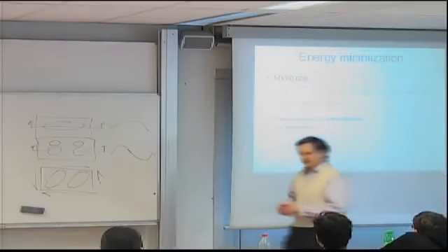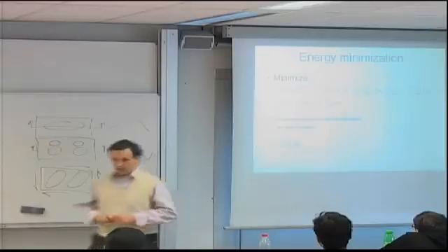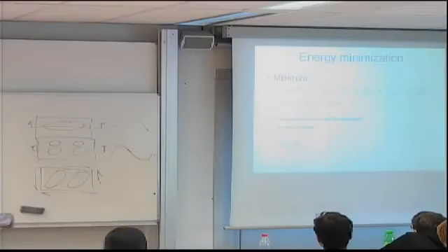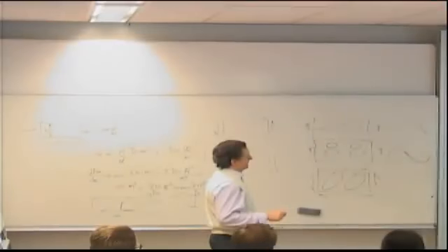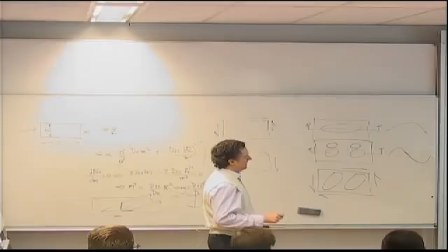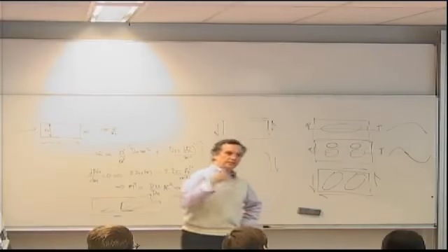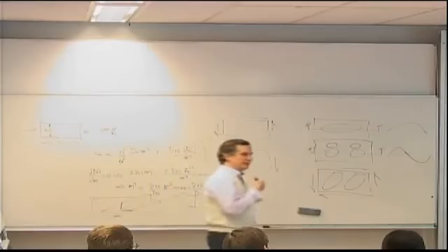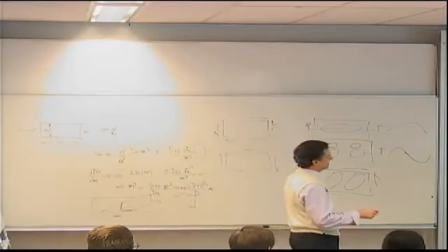So the energy, in terms of displacements for a bending problem, is this mess here. There is a potential energy term or strain energy term, which involves the D matrix, and I included D16 and D26 so that you see its general form. Remember, we said D16 and D26 are 0, so we won't need those two terms.